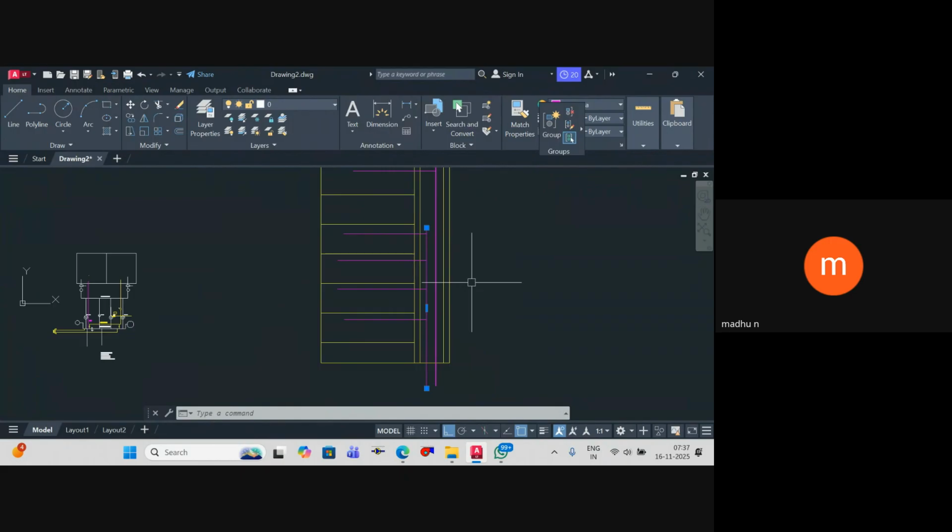But it's not mandatory. There's no rule which says that you shouldn't have two headers in the sprinkler. As I've shown in an example, you could have that as well. Understood. So you'll have one vertical, and if the pressure exceeds, then you'll have a branch orifice plate. Yes, you can install an orifice plate to maintain the pressure.